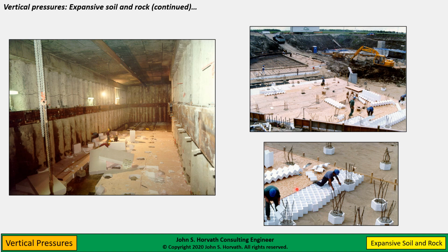You put an underlayment. This looks like OSB, oriented strand board sheets here. And this is just to support the rebar chairs and the rebar and fluid concrete. So this is stiff and designed intentionally just for this application. This is stiff enough to support construction. Comes in different grades depending on how thick a slab you're going to use. And then it's designed to sacrificially crush if the ground expands.